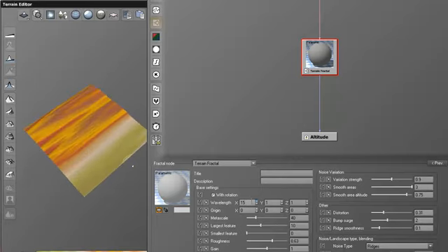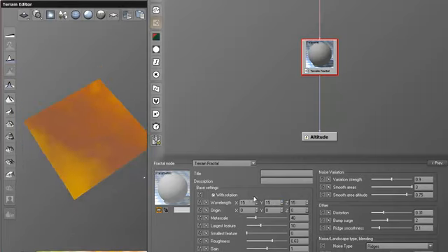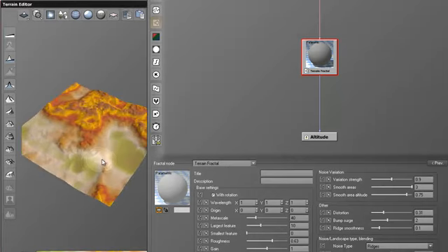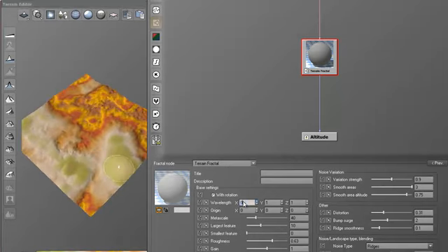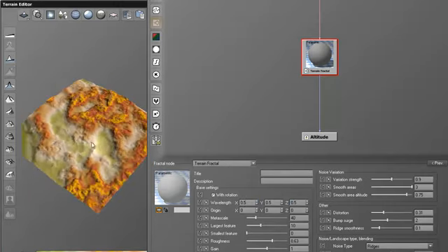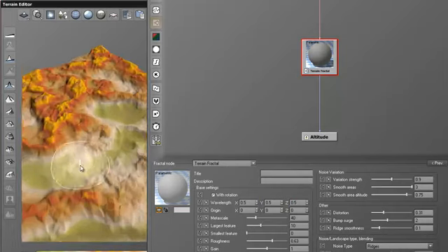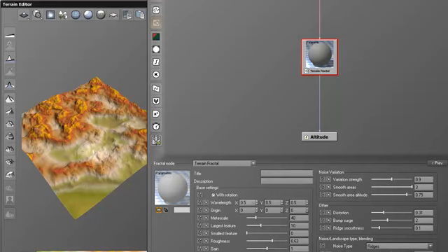And let's see, for example, if I put 15 in all the 3 axes, you can see that I have a bigger terrain. Now let's just put these ones to default and get back to our terrain. And here you can easily also put some really low values like 0.5, and you'll have a less stretched terrain or more detailed terrain as you want.